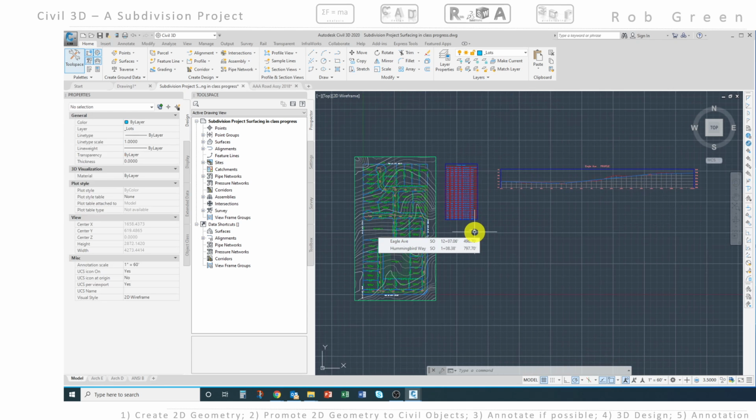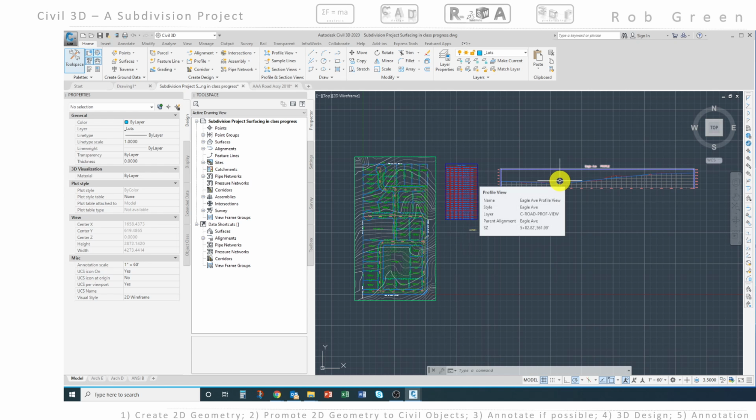So that was so fast, I guess we're going to move on to the next section, and that is where we are going to create what's called a corridor. All right, a corridor is something that combines our existing land, our design profile, and this cross section, and drags them across the existing land. So let's do that.